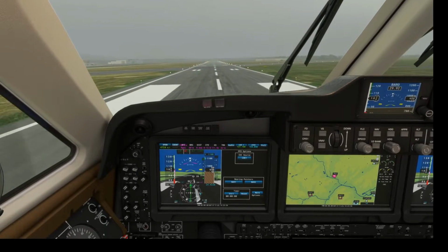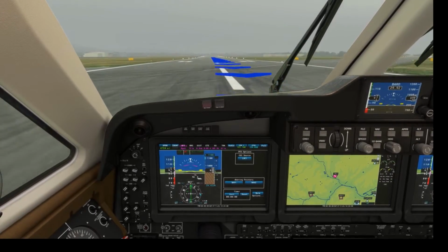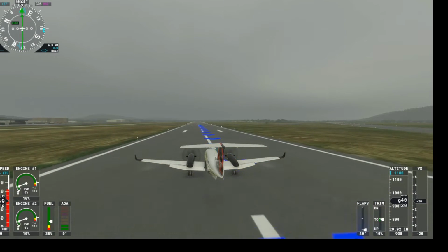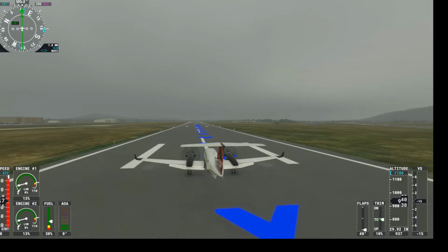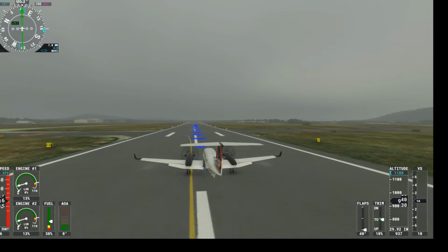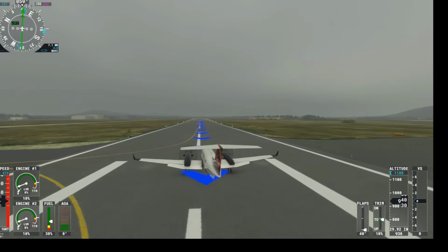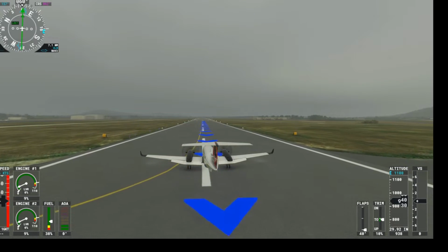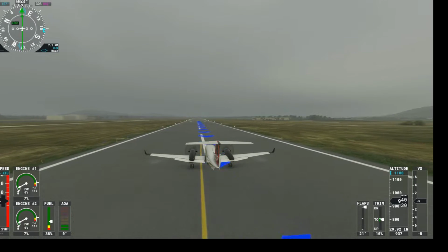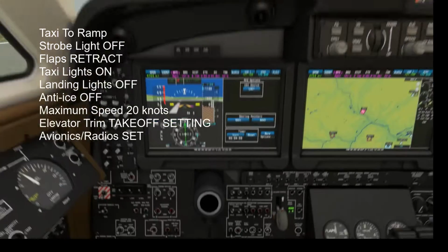Okay, so the autopilot took us all the way there on a VOR navigational course. So the King Air works really nicely for VOR flights if you want to try them. It's good if there's no ILS runway and it's just a localizer. That's basically what this would be, using VOR stations and a localizer frequency to line yourself up with the runway.